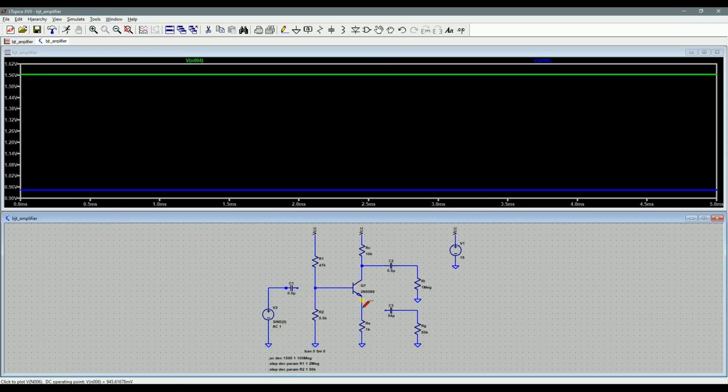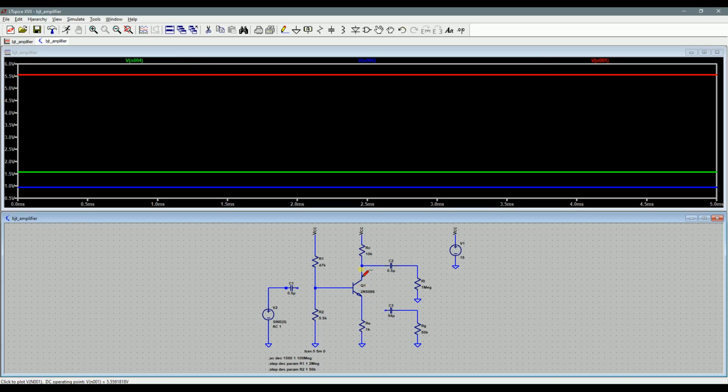So yeah, we have 0.96 volts in the emitter branch. It's a little less than what we would like, but this is a compromise that I had to make with the component values because there's only certain values of resistors out there. Now looking in the collector branch, we see that we have a little more than 5.5 volts. In the calculations we were shooting for 5, but again, that was a little offset by having to choose practical values for resistors.